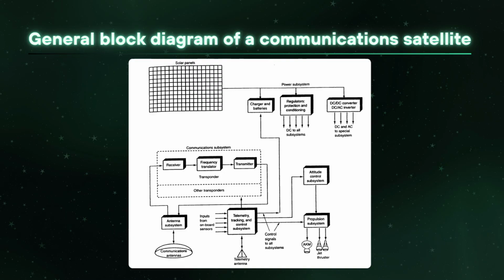An Earth station takes the signals to be transmitted, known as the baseband signals, and frequency modulates a microwave carrier. The most common baseband signals are voice, video, and computer data. These uplink signals are then amplified, translated in frequency, and retransmitted on the downlink to one or more Earth stations. The component that performs this function is known as a transponder. Most modern communication satellites contain at least 12 transponders. More advanced satellites contain many more. These transponders operate in the microwave frequency range.